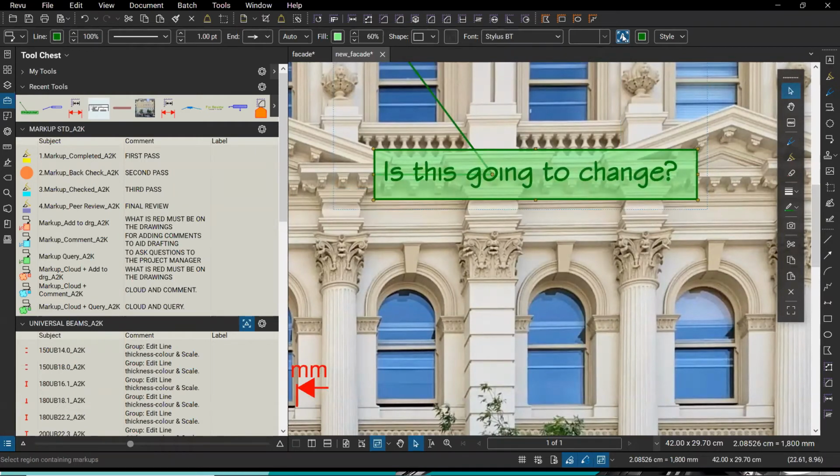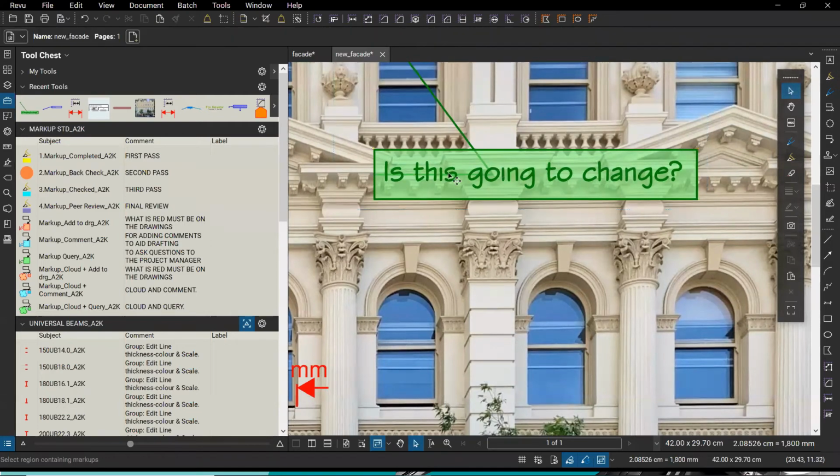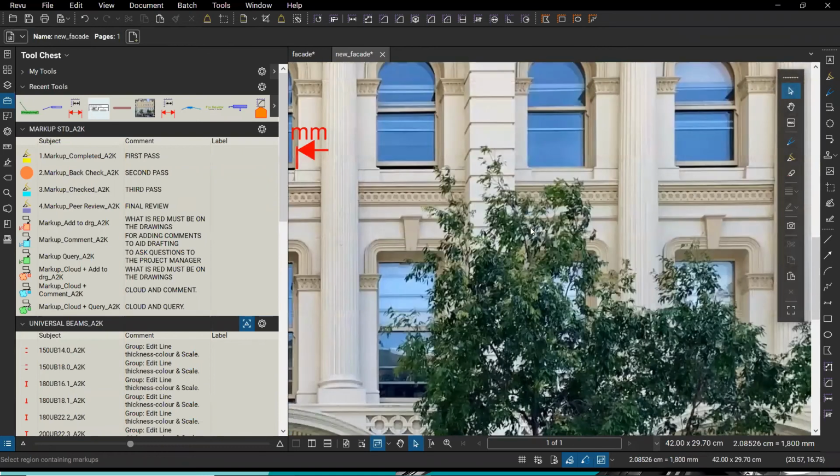So what I like to do is get it to basically how big I want it to be, and then I take off my auto size, and that will give me the actual size of the text. And then I can go, okay, well, I want that to be 15 millimeters, just because I do have a drafting background and I do get a bit pedantic.